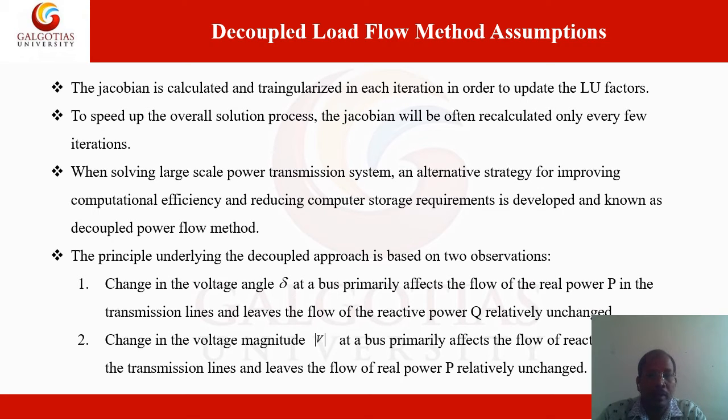First, a change in the voltage angle at any bus primarily affects only the flow of real power in the transmission lines connected to that bus, and there is a negligible effect on the reactive power, so the reactive power is unchanged. So the voltage angle variation is reflected in terms of the real power flow. This is the first assumption.